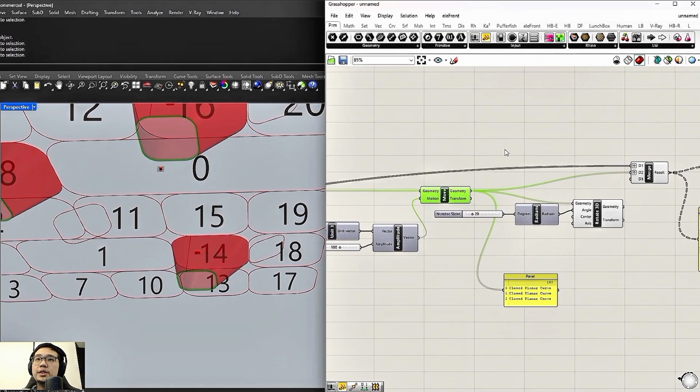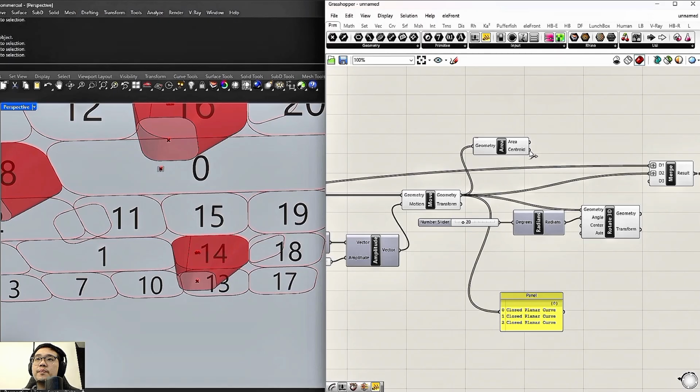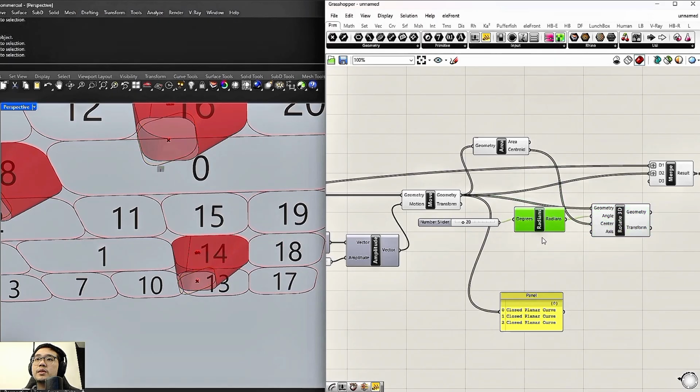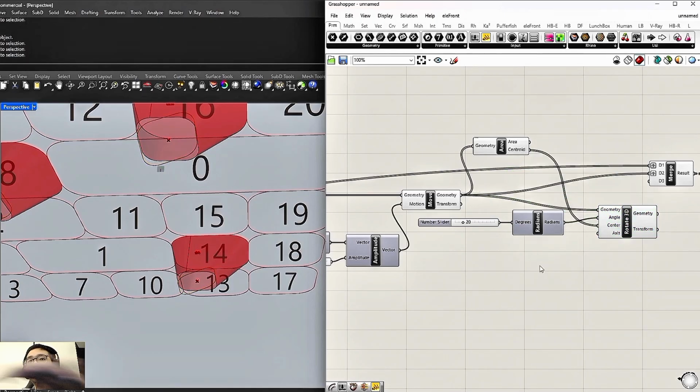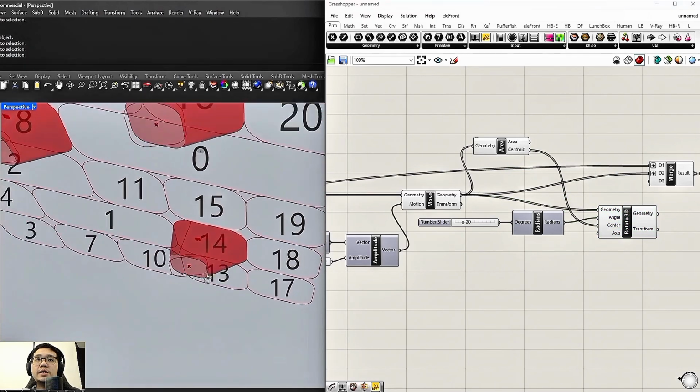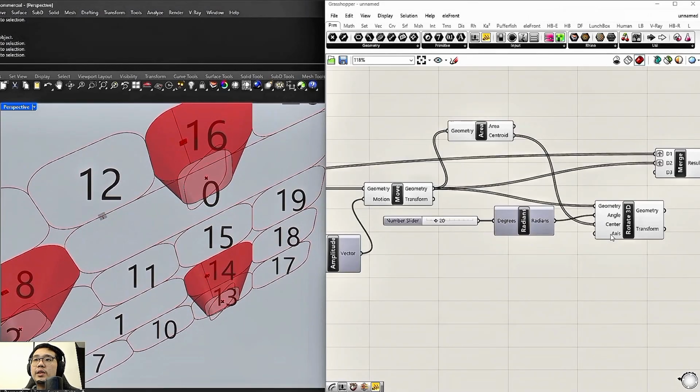So I'm gonna put in an area to get the center of rotation here, and the centroid will be my center, and then the axis we can just leave it like this for now. Currently it's set to z-axis. When it says 001, the last number is the z-axis because it starts from x, y, z. So that is fine, we will leave it like this.